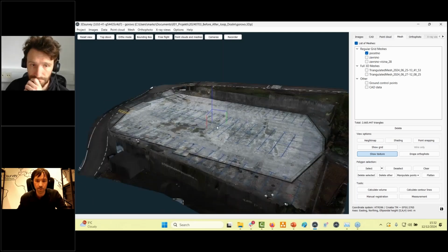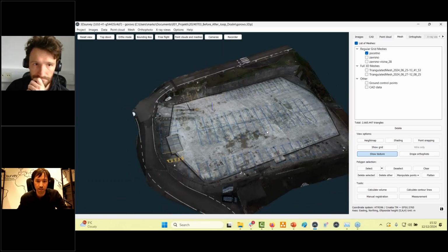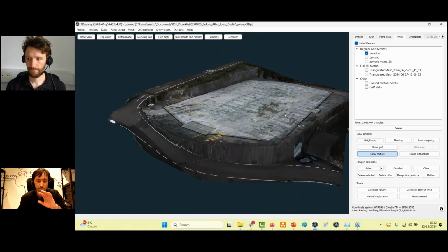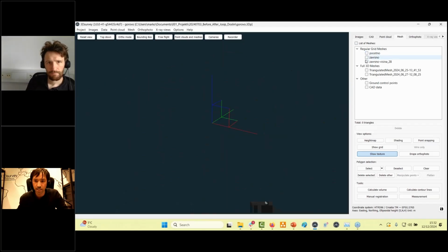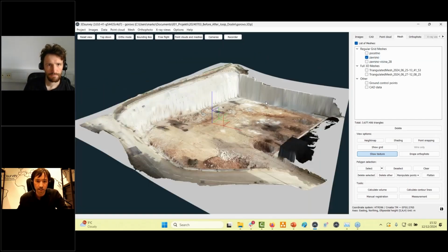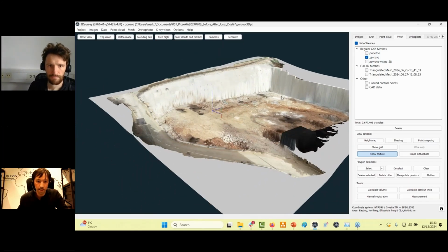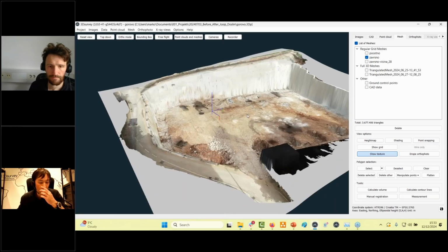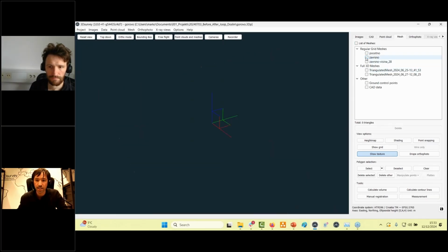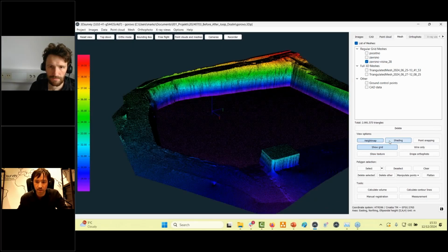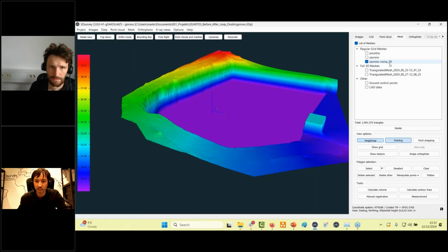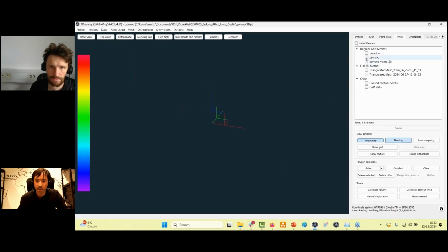This is the first surface when there was a parking slot or something like that. The point cloud is already classified and filled and polished for the volume calculation. This is already the surface. Then we have a second measurement where they grabbed a lot of material away. Probably some hotel was built there. Then the third option was actually a design surface based on a specific height. We can see it here, 28.